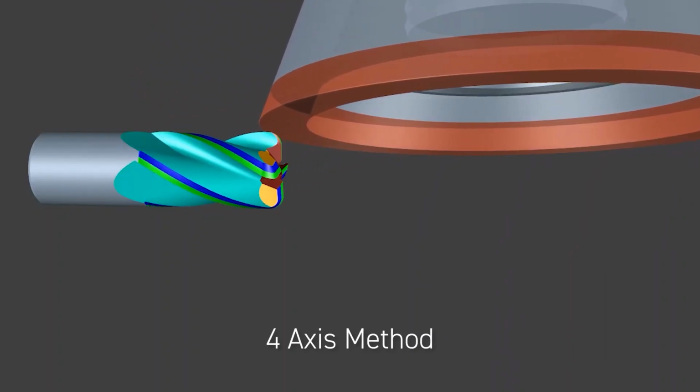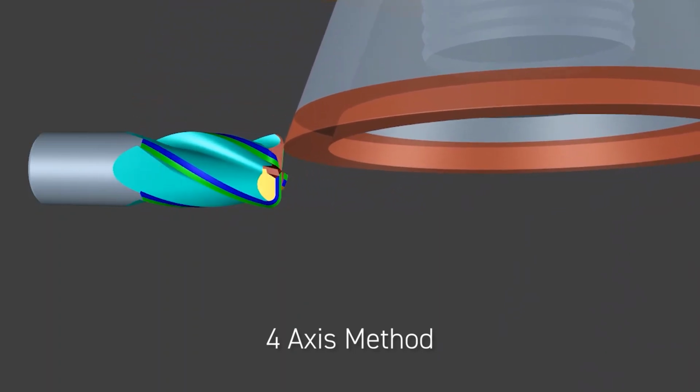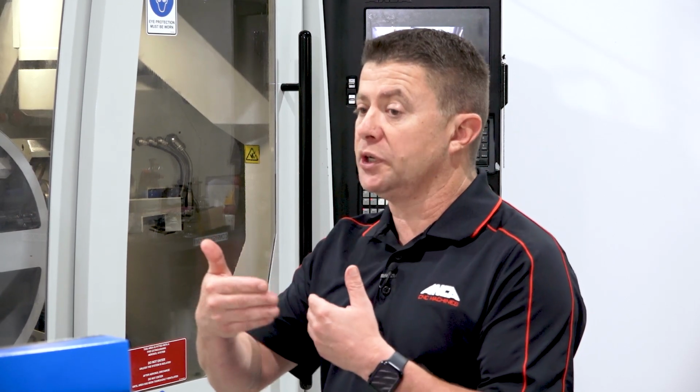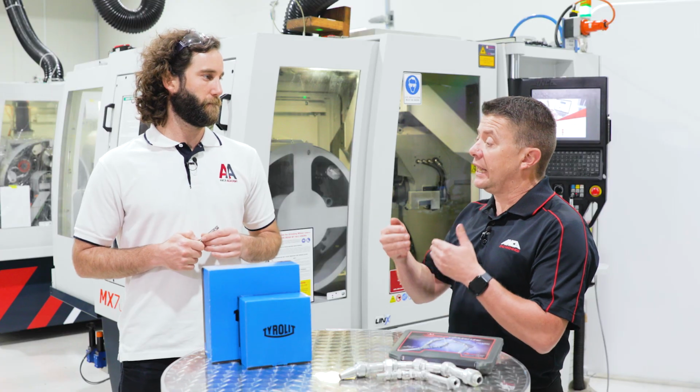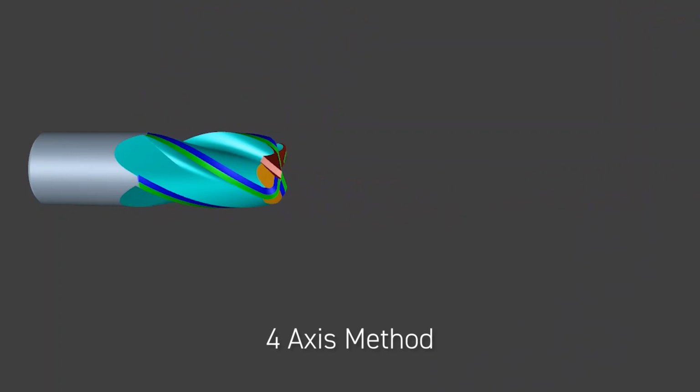Yeah, great question actually. So 4-axis grinding is used generally on smaller tools, diameter 3 and under, and especially where we're using smaller corner radiuses because it eliminates the machine movement. So we lock out an axis, so we avoid using the C-axis, and this continues to go around the radius, making sure that we get a great tool.